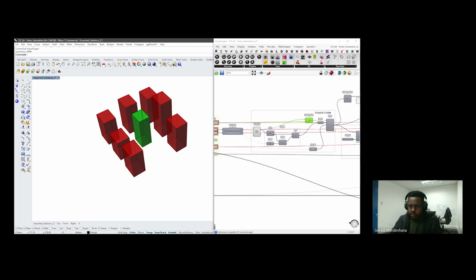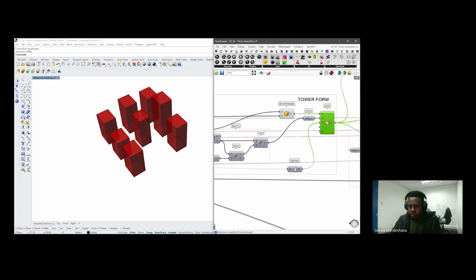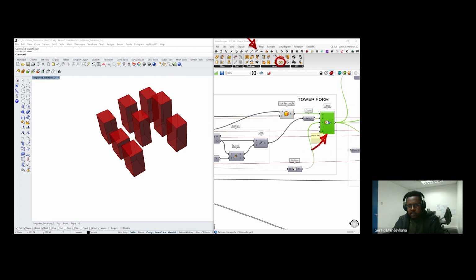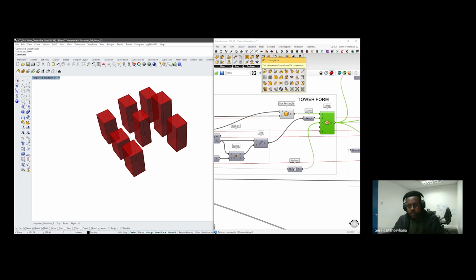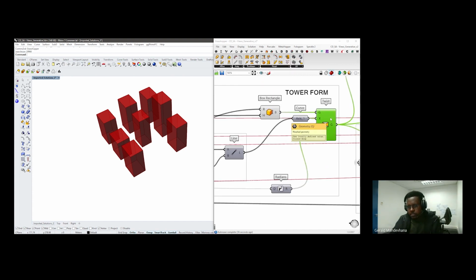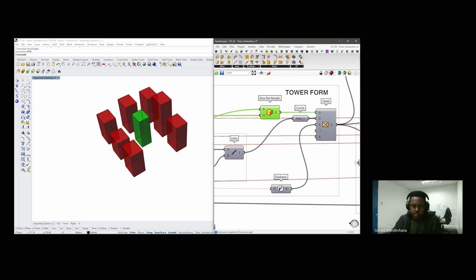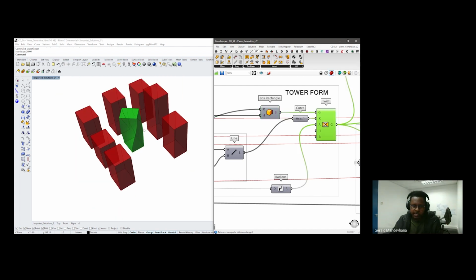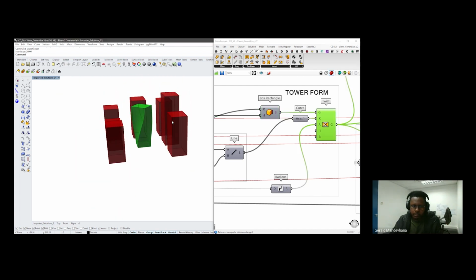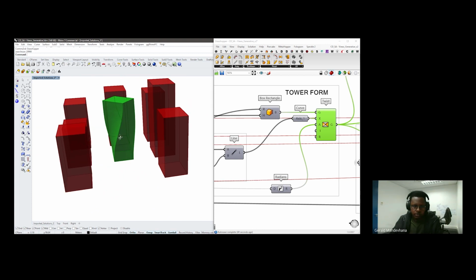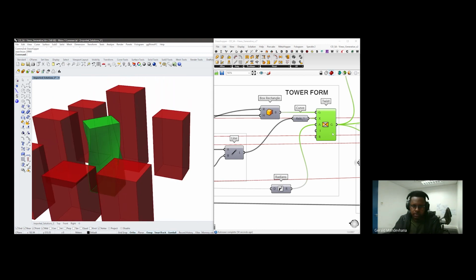In the box that we define, we then use this cool native Grasshopper component. You find it under transformations, under the morph subset. So it basically twists whatever you throw at it. So we're twisting this box to come up with that box. So once we have that, that is what we are using to define our tower.